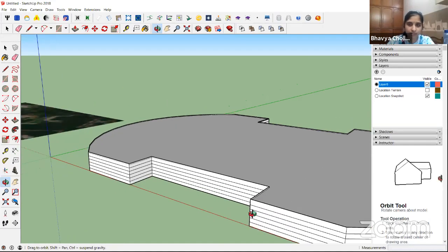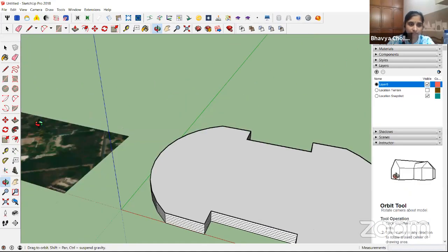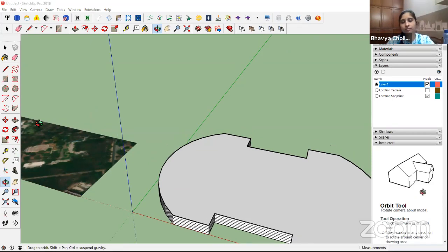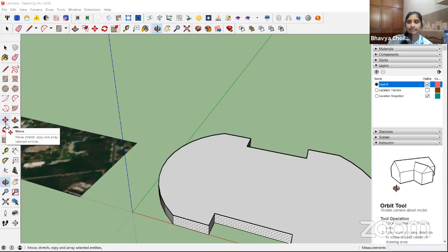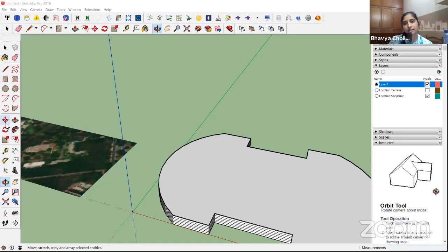Right. Now what I'll do is, this is a building, so we'll have some lift rooms above it. You'll have a penthouse, you'll have a water tank, or you'll have some pillars on it. So many obstacles which oppose the complete shadows on it. So in the live scenario, you go for the site survey. If you're in a design department, then one person from your design department goes to the site and takes pictures of all the things on the building when you want to install the solar, and all those parameters will be designed in this modeling.